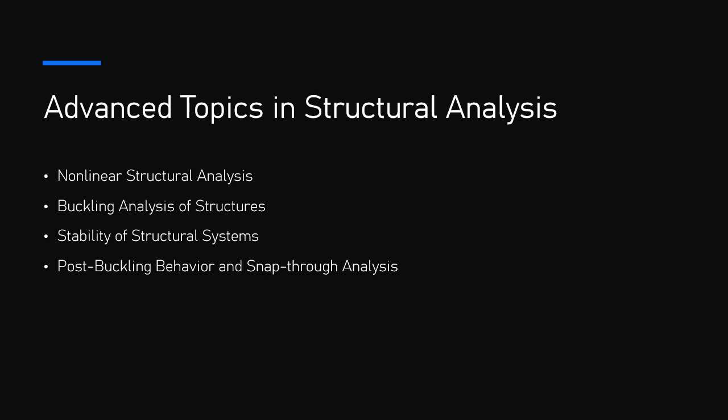The stability of the structure is influenced by its stiffness, the geometry of the cross-section, and the length of the beam. 4. Local buckling. Local buckling occurs when parts of the structure, typically thin-walled members such as plates, stiffeners, or shelves, buckle locally under compression before the whole structure reaches the critical buckling load.